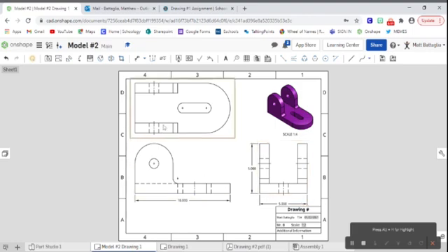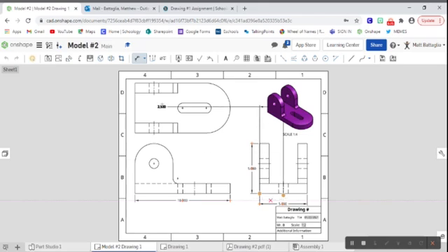All right. So one of those dimensions comes, well, actually, let's focus on this side view first. Let's go ahead and handle this. The first one is coming from this edge to the center point here. So it's measuring from the edge to the center point of this hole right here, and that's 2.5 inches. So we'll go ahead and place that 2.5, and that looks good.